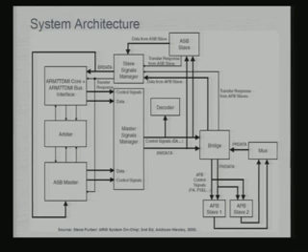Now, if you look at the complete system architecture, it would look something like this, and you should note this carefully, because it tells you how a complete SOC architecture internally would look. We are looking at using ASB; these are all ASB masters, and this is your ARM7 core, which would communicate with your arbiter.